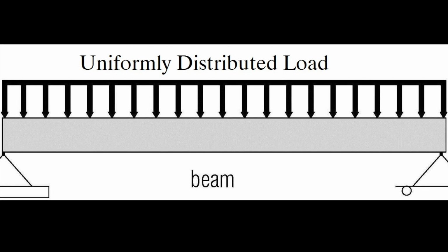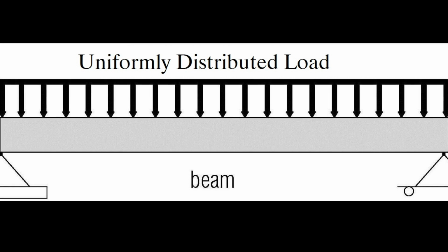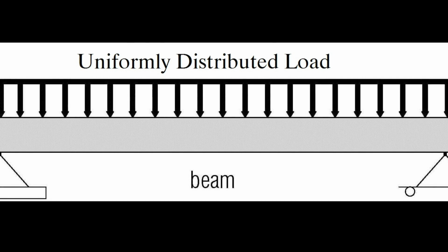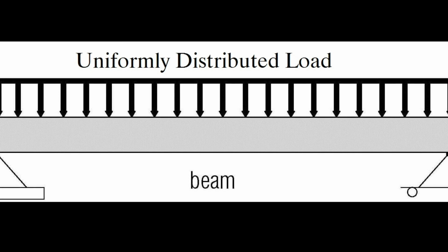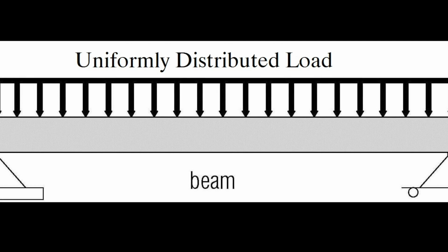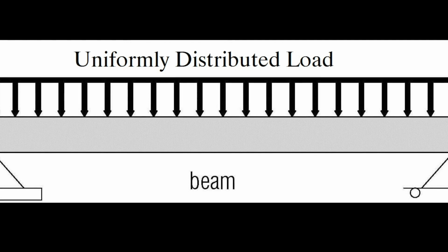1,028. We then multiplied that by half of the bridge, which is 8.2 meters. Then we subtracted 10.7 meters, and then multiplied by the length of the bridge, which is 16.4 meters, to find the reaction force of the small section of the bridge, which was 59.35 kilonewtons.